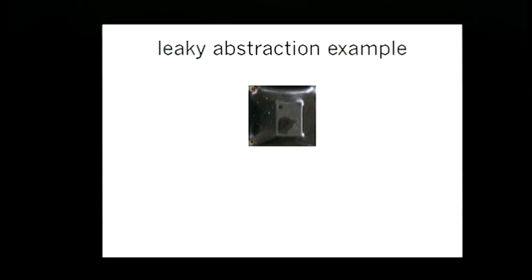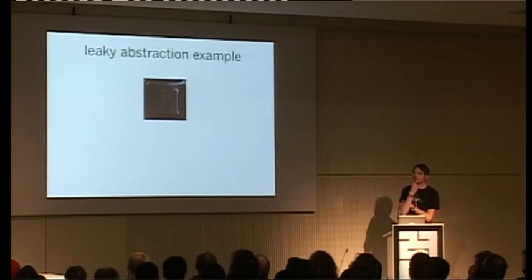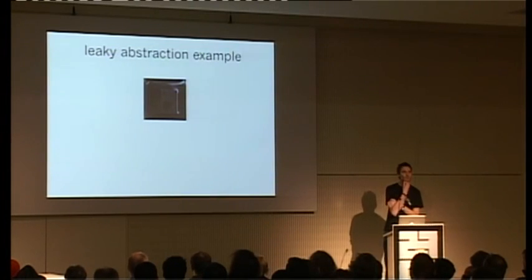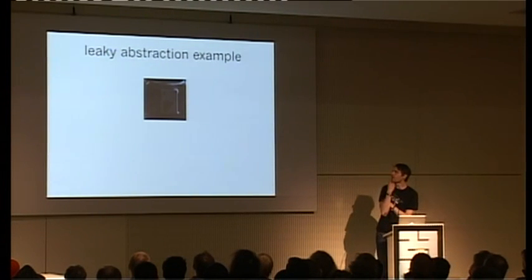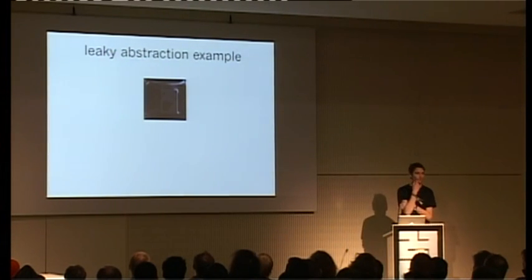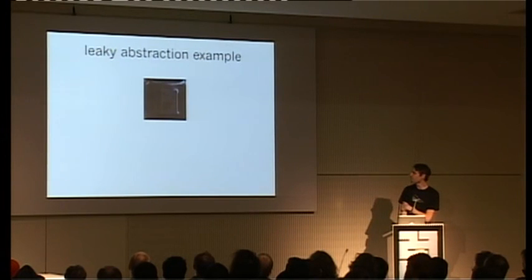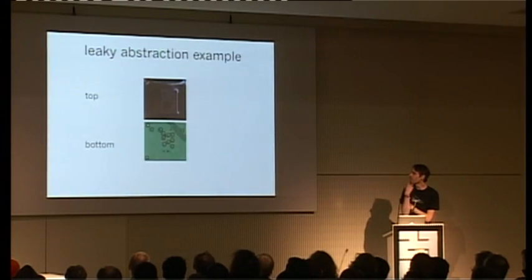So here is a nice chip on some board. There's some epoxy sitting on top. The epoxy is meant to make it hard for you to touch the pins and tap them, or to desolder and remove this particular chip. I guess it stores some secrets, but the problem is that on the bottom of this board, all of the vias are exposed.